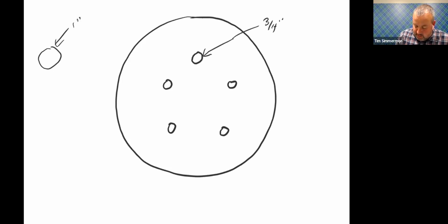that means that the position of this can vary a little bit by roughly 1/8 of an inch each way, right? It'll allow it to shift over, because if it's 1/8 of an inch all the way off to the right, it'll still go inside that 1 inch hole. If it's 1/8 of an inch off all the way to the left, it'll still go into that 1 inch hole. If it's perfectly centered, it'll go in there too. That would be ideal, but we need tolerances for manufacturing.